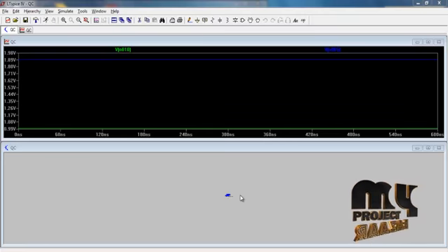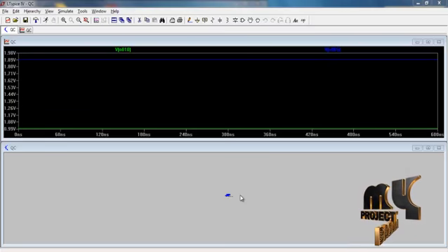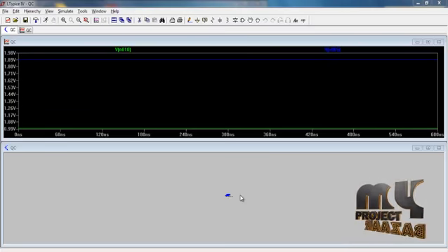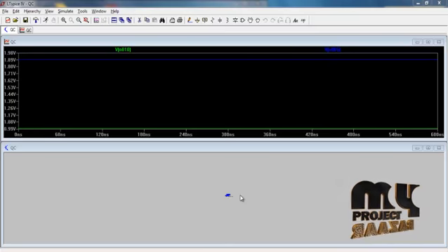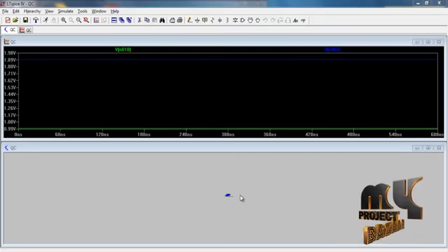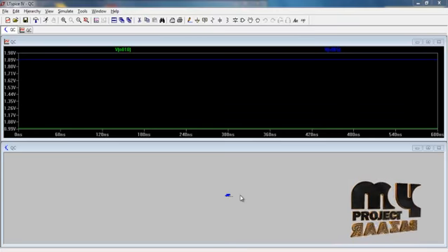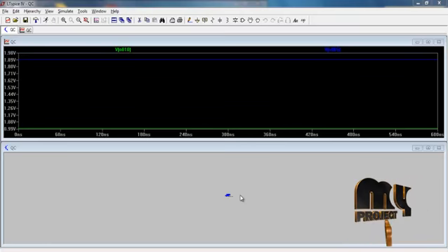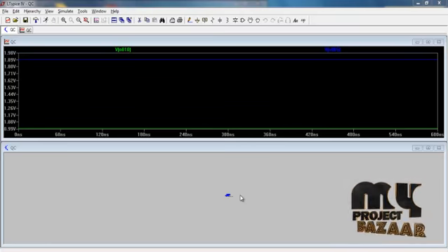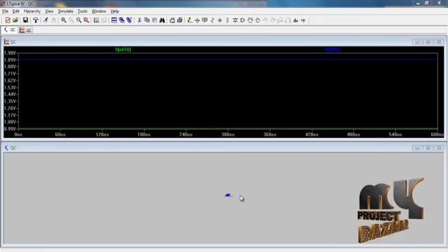Both quasi-circulator and bridge-T network utilize the inherent non-reciprocity of transistors to suppress S13. The small values of S31 and S13 are also assumed, and therefore P1 and P3 are mutually isolated. The capacitors C3, C4 and the feedback resistor are the basic elements of the BTN. The cascode topology consists of the common source CS stage and common gate stage for improving the isolation of S12, which can also be recorded as the external amplifier.